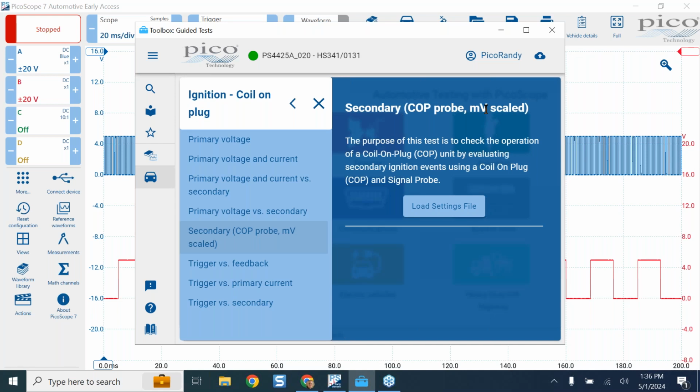So just something that I always mention because, again, pain point. Why isn't this reading kilovolts? And why is it reading millivolts? That's because that's the direct reading out of the probe. We don't convert it or guess what it's going to be. Well, we quit that, and I'm glad we did, actually, because it was just more of an estimation than anything. Okay, so I'm going to go ahead and just exit out of here.